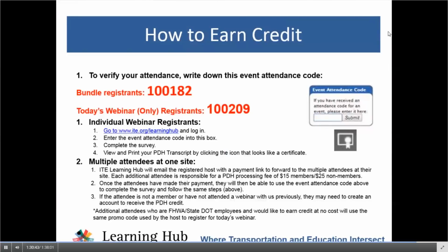The one thing that the committee has done with all the methods now is whenever we get a VC ratio of 1.0 and greater than that, we've said that that's LOS F because the expectations are matched up with this.